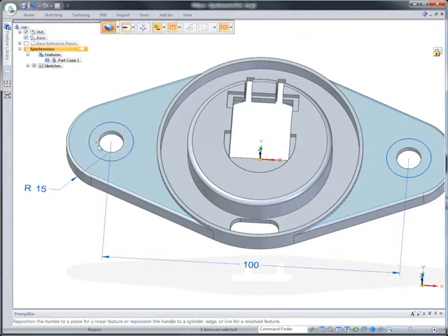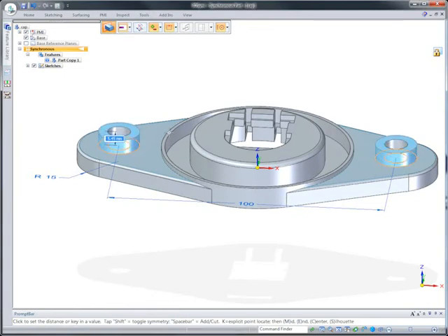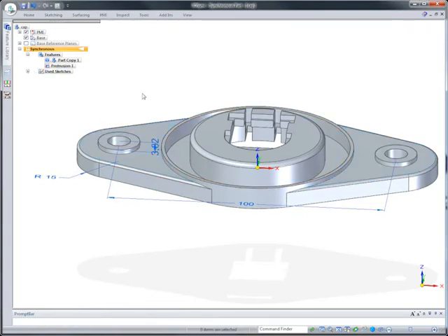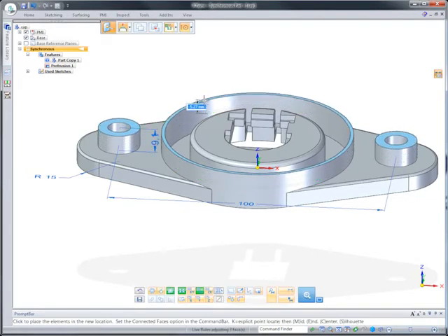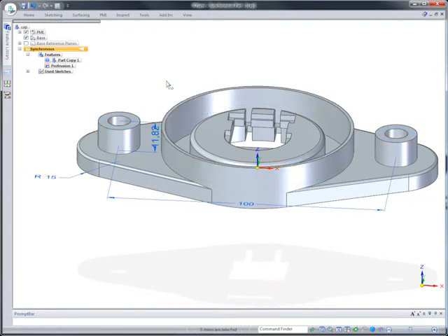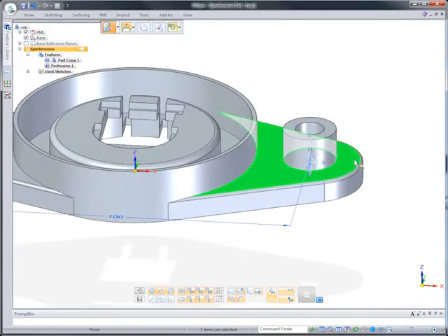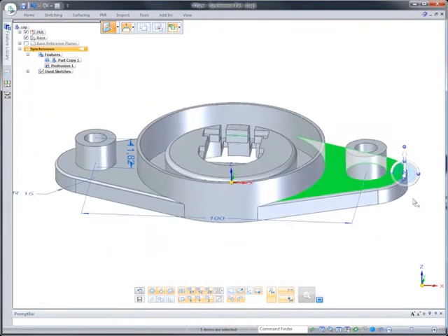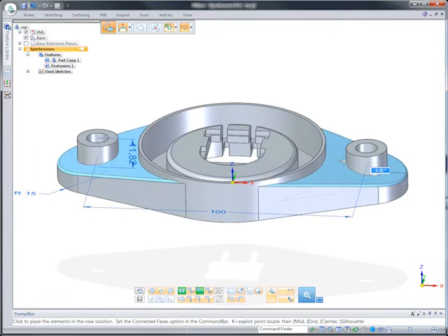Next, we'll quickly generate new 3D geometry from a familiar 2D sketch, resulting in a couple of new mounting bosses, their height driven by existing geometry. As the center face is edited, the mounting bosses update. Faces can also be rotated, and live rules unique to synchronous technology finds and changes symmetric counterparts, ensuring the original design intent is kept.